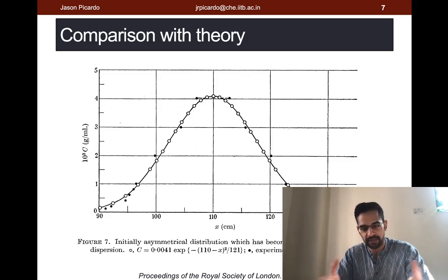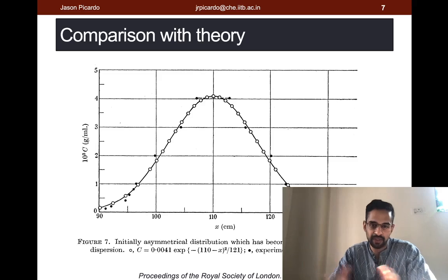So in many problems, the tubular reactor is one, we are not really interested in knowing all the detailed variations throughout the domain of our field of interest, let's say the concentration. What we really need to know to optimize the system or to design a better engineering system is the average concentration. So we would like to know the average conversion or the average outlet concentration from the plug flow reactor, for example. And so to design a better plug flow reactor, we just want to optimize the total conversion or the average or the RTD profile, let's say.